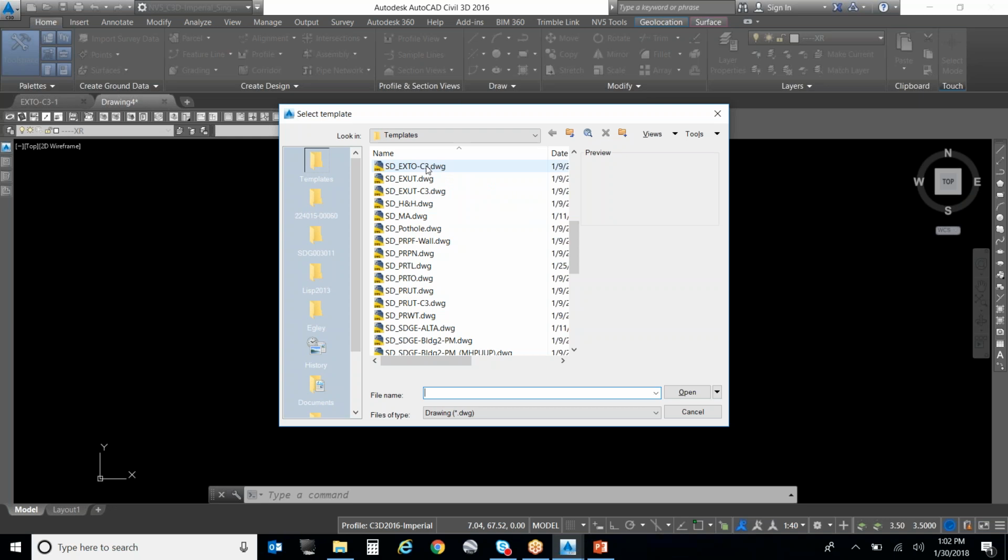So one of the first things that you need to do is start a new drawing, but start it with a template, okay? How many people take the file we receive from Inland and run with it? That becomes a simple rename as EXTO. Everybody in here that creates surfaces should raise their hand. I see it all day long. We see it almost every single day. I can't tell you the number of errors that stem from this. Your guys' life will be made so much easier if you follow this protocol.